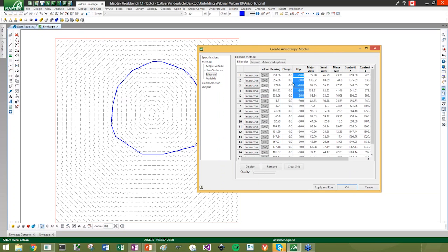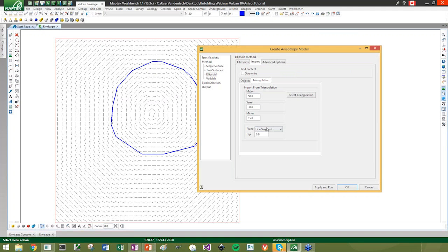It'll smoothly interpolate them. When you're coming from design data, however, a single line only defines 2 of those angles. It doesn't define the third. So in the import option, you have to specify a plane which will be used to get that third direction.